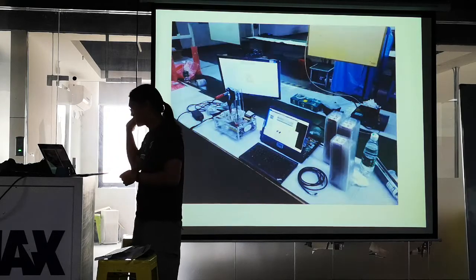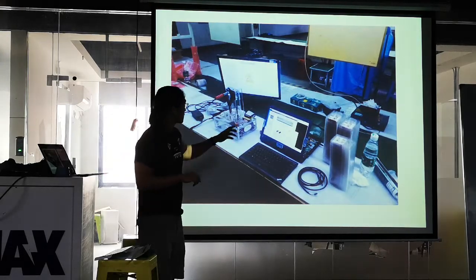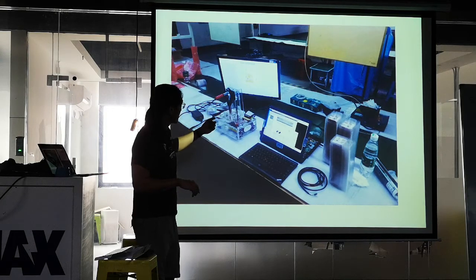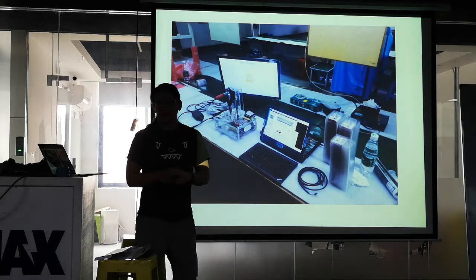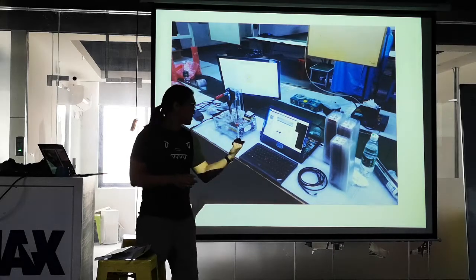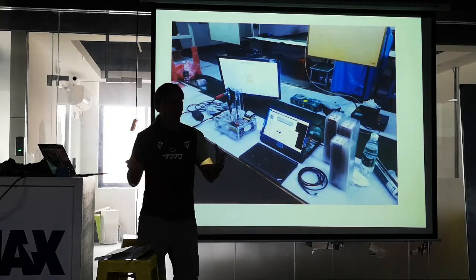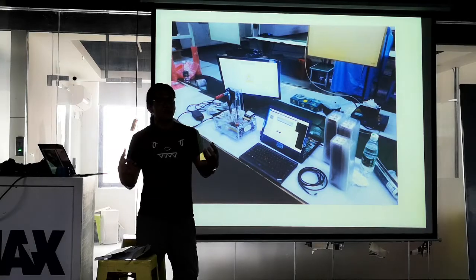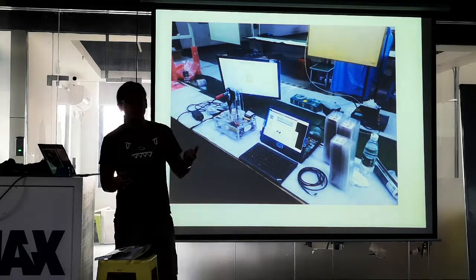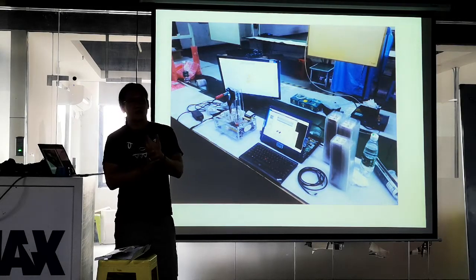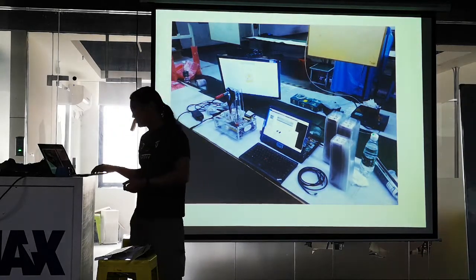This was an example of a TV-tronics product that we had done back in the day. It was like this little sticker that had an ATtiny85 on it, which is a total low-end 8-bit microcontroller. The point is that the test jig for it had a full Linux computer on the inside, a full Linux SBC. So even though your product was this tiny little 8-bit controller, the test jig itself had by far more complexity. I finished the circuit board in an afternoon, but the test jig itself took about 2 or 3 months to complete to get this to production.